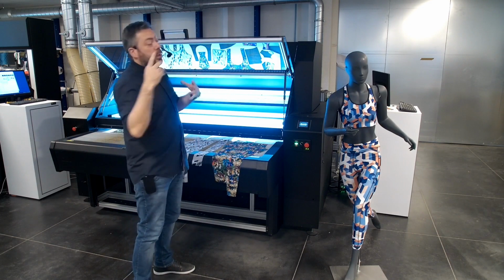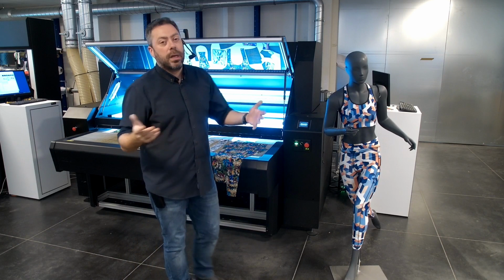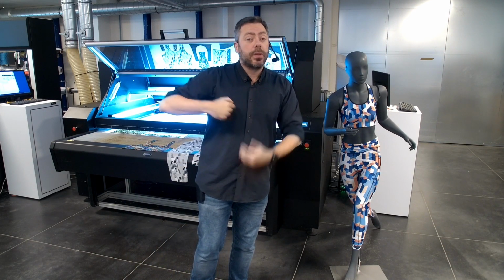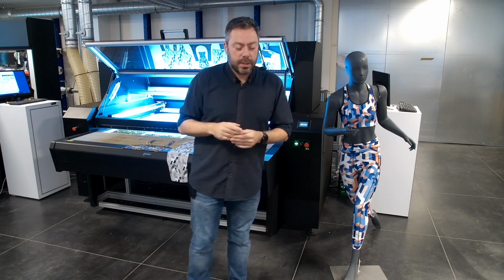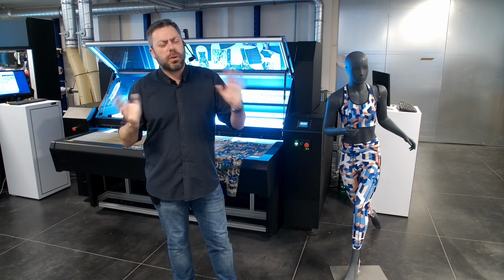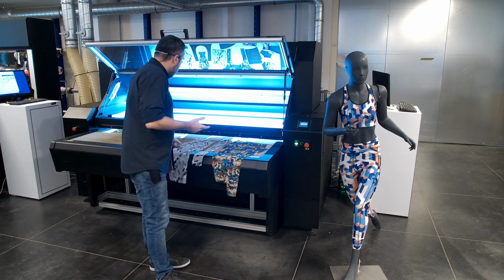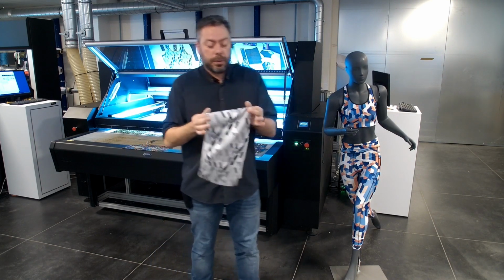Now, what we do need for this is a black outline around each shape. Why? Well, if you have, let's say, a white garment piece where you only have a small logo on, you need to have a black outline, because white on white material is going to be difficult to recognize where everything is. So the only prerequisite here is to have a black outline, about 2 or 3 millimeter in general. By adding the black outline, our software will scan, detect it, and then you're able to cut it.